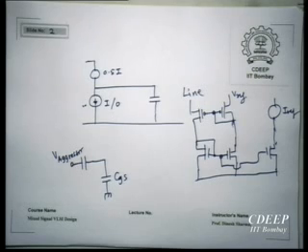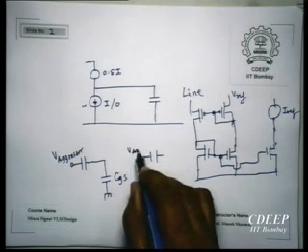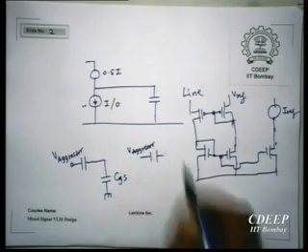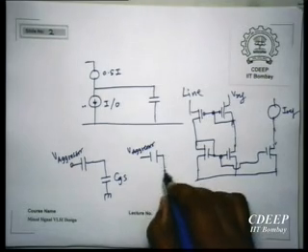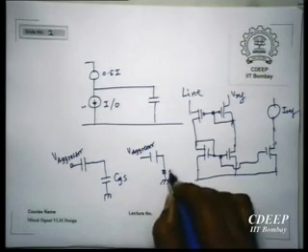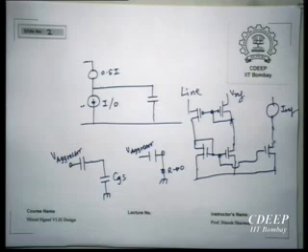In the current case, what happens? You have the same V aggressor, same capacitance, same wire, except that it is coming down to an input impedance which is very, very small. So as a result, the noise voltage which results at this terminal is very small. That is one thing. But in fact, things are even better.